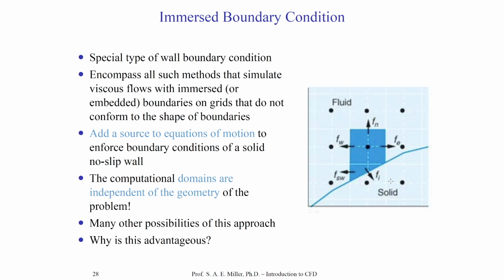The disadvantage, of course, is it is computationally expensive, and you'll never exactly resolve the very complicated shape of the boundary, which you might be able to do with explicitly setting grid points and velocities to 0 at the wall. But you can see it completely removes the difficulty of the grid generation problem, which we talked about earlier, and consumes the majority of the user's time.